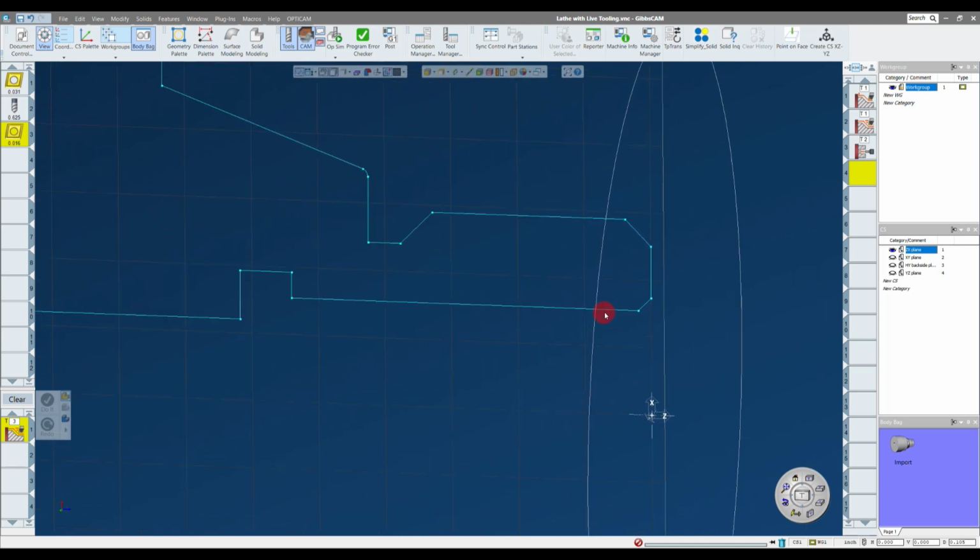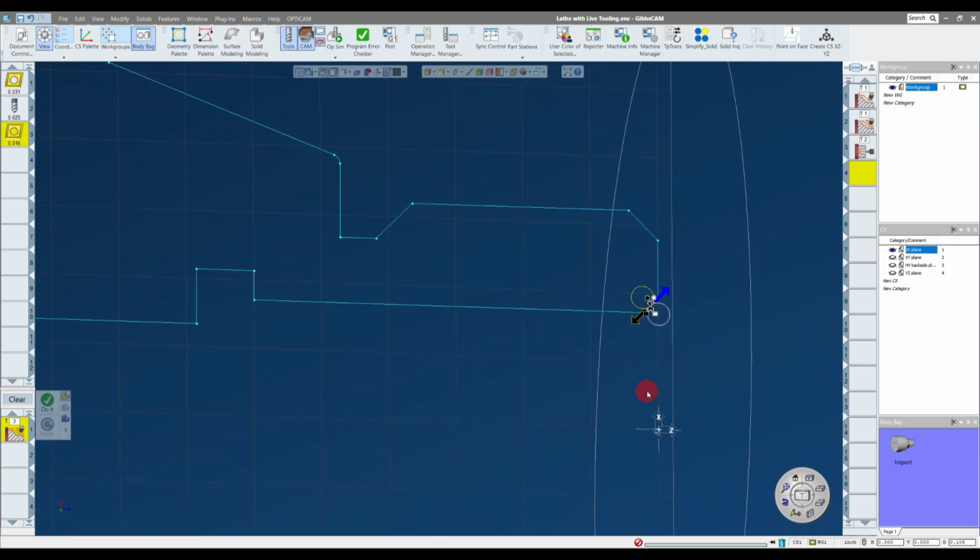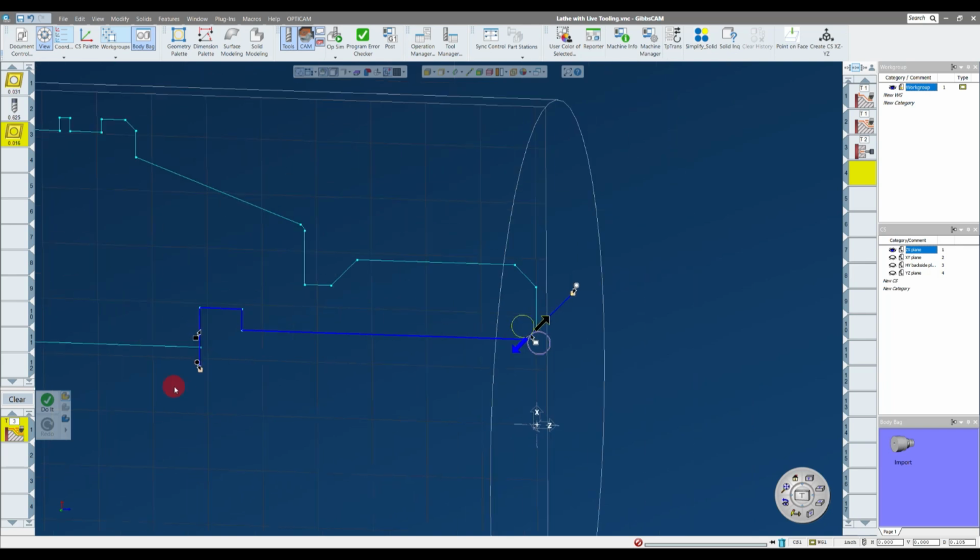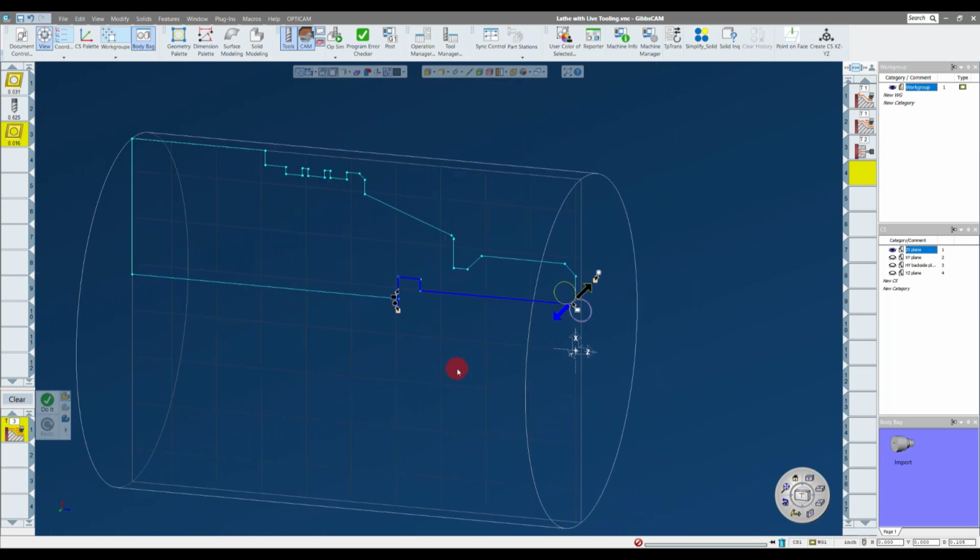So in setting my machining markers, I do want to start on the chamfer of the part. I'm going to extend my cut here. I'm going to cut in this direction. Now again, I need to set my black circle and black square at this vertical line. So I'm going to use Control and Shift and set my end markers to that line there. And I'm going to bring my extension down into the hole that I drilled.